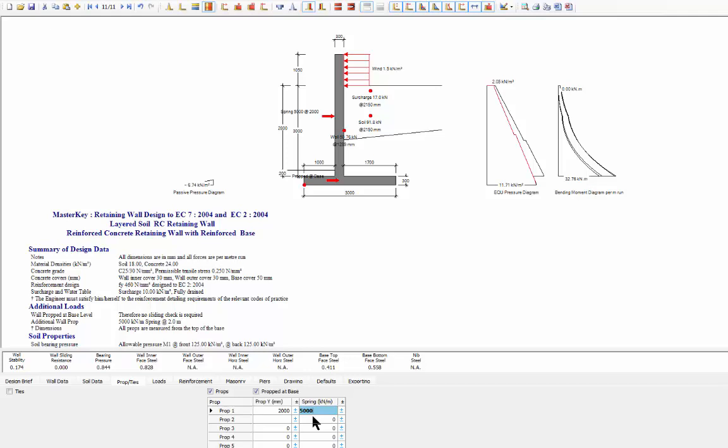It is beginning to affect the bending moment diagram, and only just. So that's 5,000, 50,000 kilonewtons to move the support by 1 meter. That is quite a large load. So there's our prop back in again.